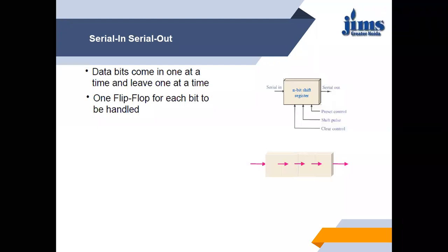And in your current scenario, whatever processor you are using, either in your mobile or in your laptop or computer, you are using a 64-bit processor. That means for a shift register which is capable of handling a 64-bit microprocessor, you need 64 flip-flops in that particular register so that it can store 64 bits in parallel. So all the theory will be discussed on the 4-bit connections.